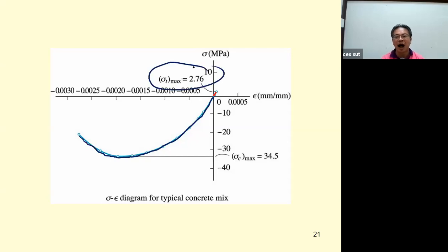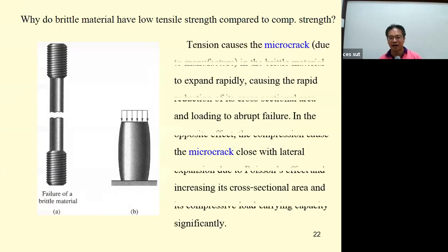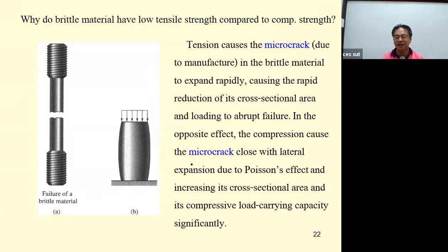That produces very low tensile strength. However, when you put the concrete in compression, the micro cracks just crush each other, and that's why the concrete has this high compression capability. Okay, you may read from this.